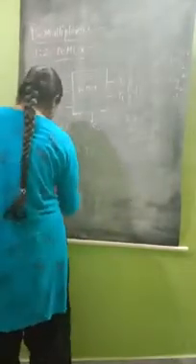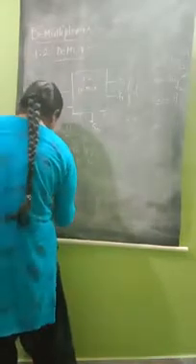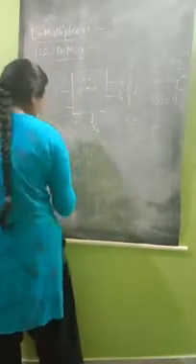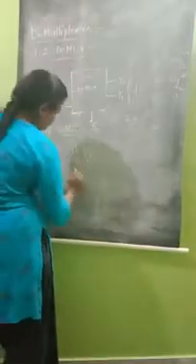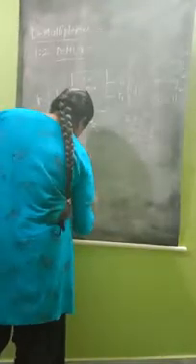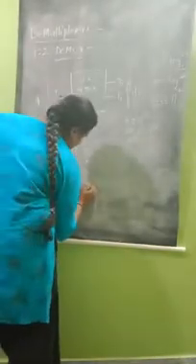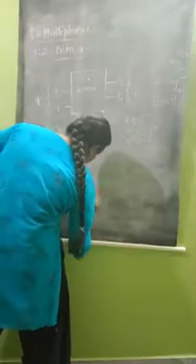When the enable is 0, the circuit is completely off, so with S0 equal to 0, y0 is 0 and y1 is 0. Then with enable 0 and S0 equal to 1, the selecting line takes 1 but the enable is 0, so the output is also 0. When enable is 1 and the selecting line is 0, the input appears at y0. When enable is 1 and the selecting line is 1, the output is shifted to y1.